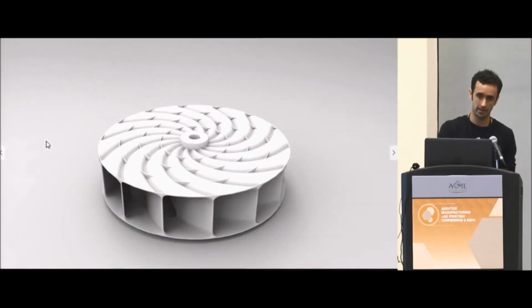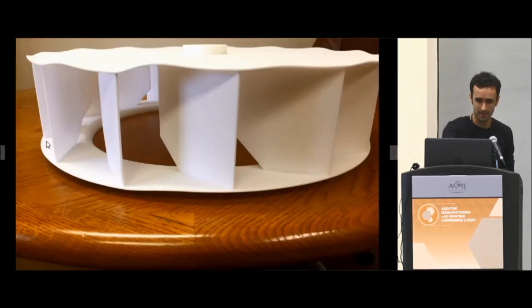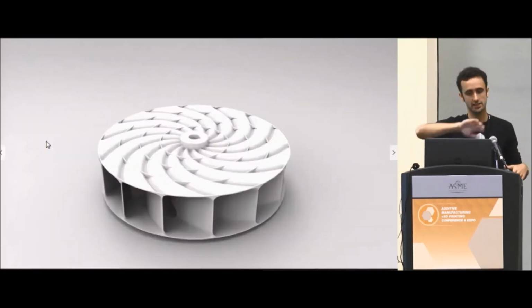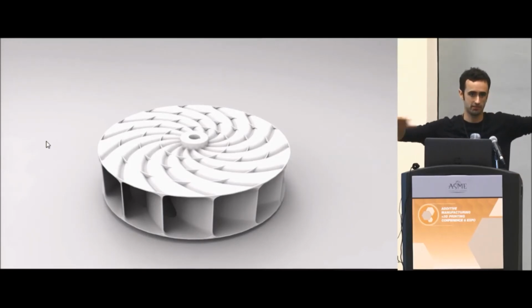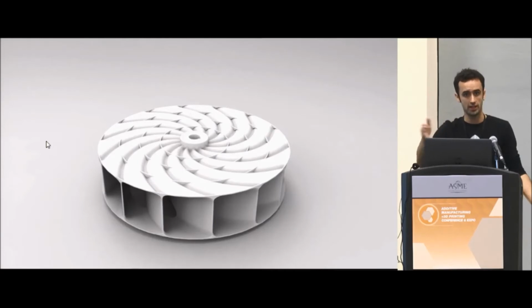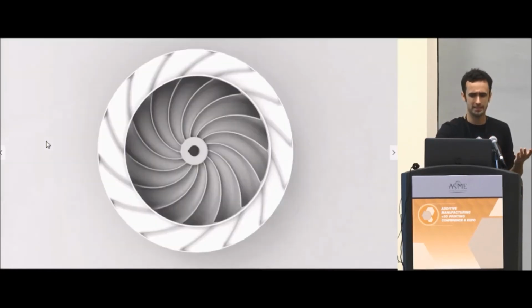And so this was what we made, which we just printed, and it actually didn't warp at all. We basically turned these really thin, flat cross sections into arches. And the arches won't warp, basically. A big flat sheet of plastic has a tendency to warp because of different thermal stresses, but if it's a nice arch, it contains those stresses much better and it doesn't warp.